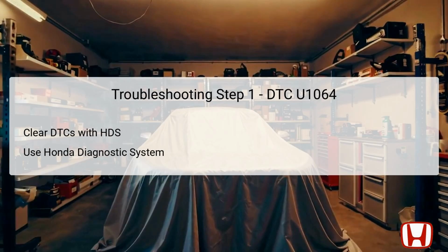The first troubleshooting step involves using the Honda Diagnostic System, HDS, to clear any existing diagnostic trouble codes, DTCs. This step is crucial because it helps establish a clean slate for diagnosing the current issue. By clearing the codes, you ensure that any intermittent faults recorded in the system do not affect your troubleshooting process.